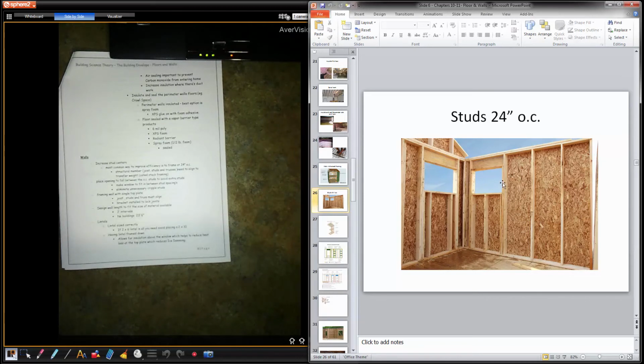And then once the drywall goes on, you're going to screw drywall screws every 8-inch, probably around the perimeter of that, maybe every 12. So you probably have a drywall screw here and a drywall screw here. Well, drywall is somewhat structural, not really, really structural, but it does help with rigidity. It stops things from twisting. So that'll hold those 2 pieces together. So there's no need to put that 2x4 here and that 2x4 here. That's just taking away insulation.